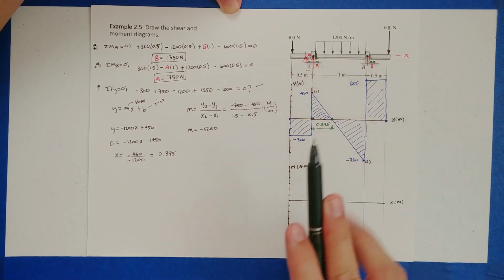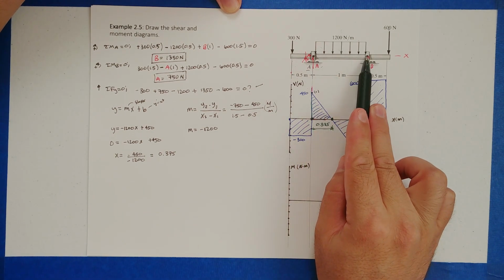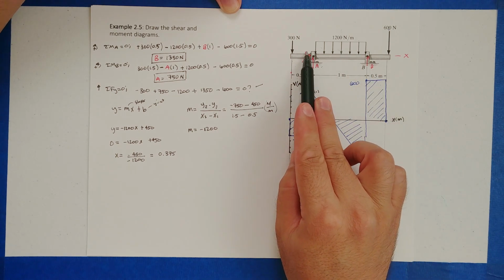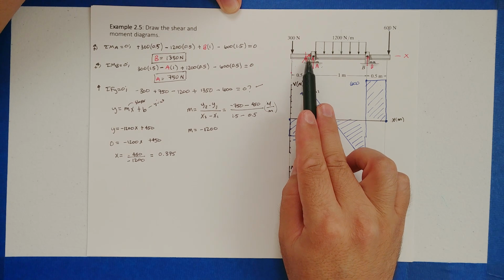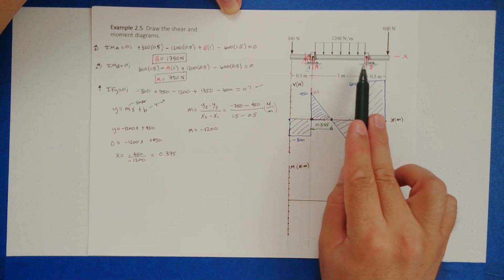at A and B. When we look at this picture, we can see here, this is going to be a thrust bearing, and that's a journal bearing. However, in this problem, we don't have any side loading, so there's not going to be any need to develop an X component to the thrust. So that's going to go to 0. So we really just have a force in A and B.